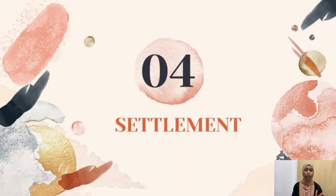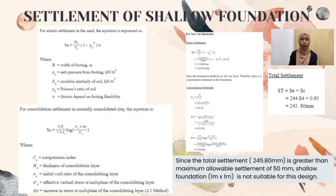The fourth job scope is settlement. We must check the settlement of the borehole foundation in order to identify whether it is able to support the load from the structure buildings or not. The first one is settlement of shallow foundation.